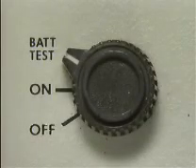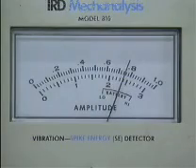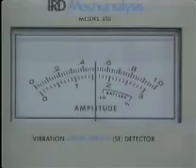If a vibration meter is powered by a battery, the battery should be checked before any readings are taken. If the battery is in good condition, the indication will be within the range of the battery voltage level scale. If the battery is weak, the indication will be below the low end of the scale. Any readings you take with a meter that has a weak battery may not be accurate.